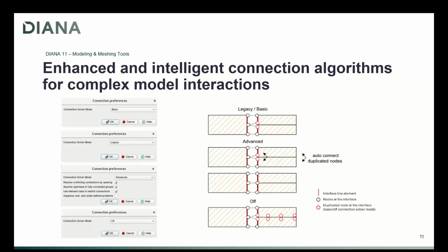Therefore, it may be necessary to reunite coincident topology that is either part of the source or the target of the connection, but is not part of the connection itself. As a result, and people who have been dealing with the modeling of interfaces understand what I'm saying, the creation of interfaces introduces coincident nodes across the interface, which share the same coordinate but belong to different elements across the interface. And when there is a geometry boundary touching either side of the interface, the node is split at the intersection, which is not desired for most of the cases.